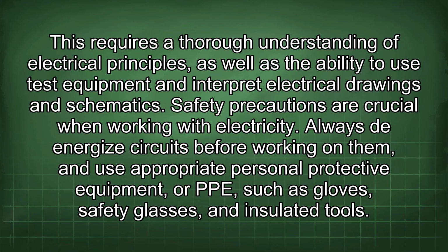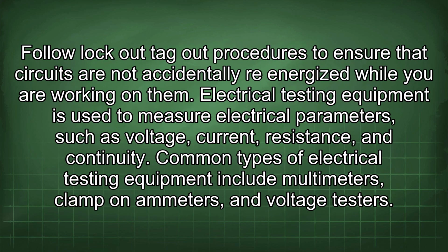Always de-energize circuits before working on them, and use appropriate personal protective equipment, or PPE, such as gloves, safety glasses, and insulated tools. Follow lockout-tagout procedures to ensure that circuits are not accidentally re-energized while you are working on them.